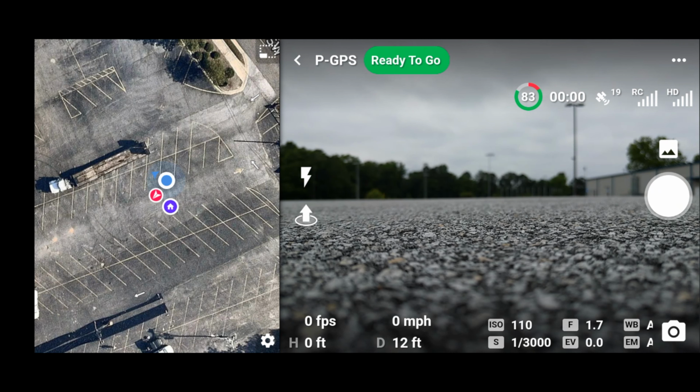Alrighty, guys, back on the app. I have the Dronelink DJI app still in beta. As you can see, we're at the park. We're ready to go. A couple things to keep in mind: on the controller, you must have it in normal mode, and through the DJI Fly app, you also must turn off obstacle avoidance, or the joystick will not be able to do the virtual mode.